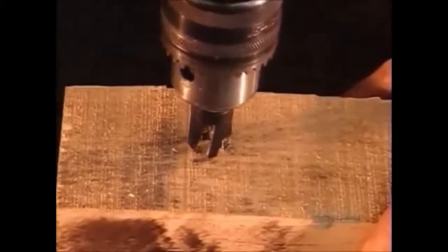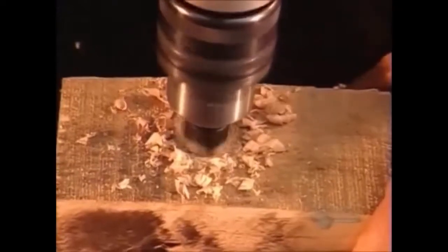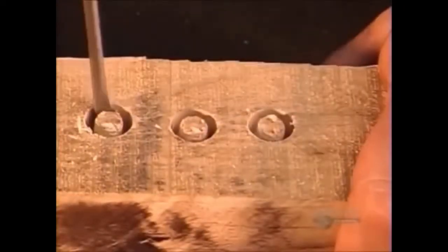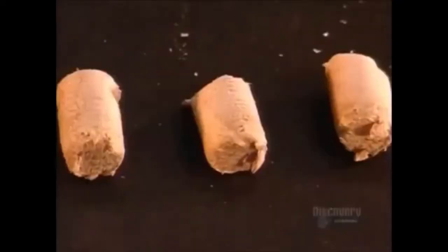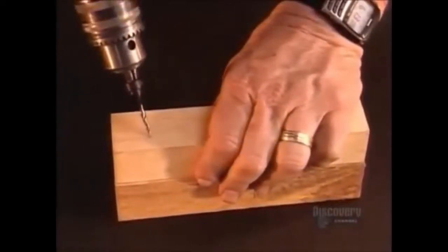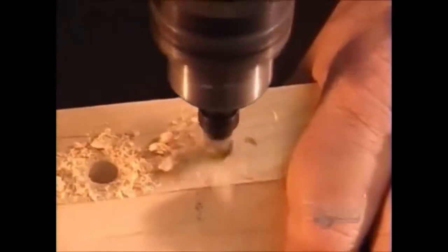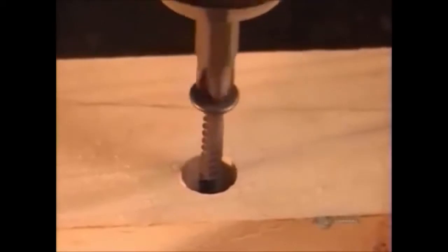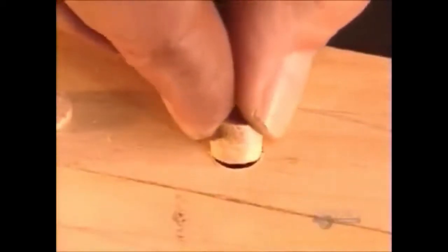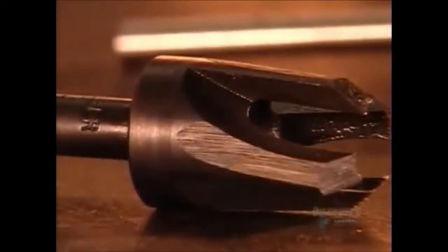So, how do the 3 drill bits we've seen all work together? First, you use the plug cutter to make the plug. Then you pop out the plug with a screwdriver. Next, mounting the countersink, that black tool, onto the taper point drill, you drill a hole for the screw. Then you drive the screw into the hole, sinking it below the surface. Then you cap the hole with the plug. These tools come in an extensive range of sizes and grades for both amateur and professional woodworkers, and for industrial machines.